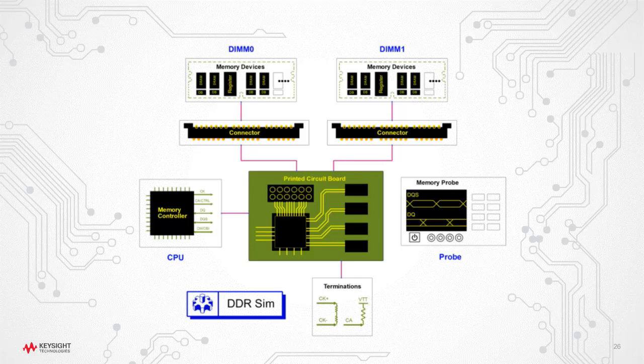Oh yeah, sorry, we just covered that one. So the short answer is yes, it can, and the longer answer is that for DDR5, you need to be able to run transient to capture the characteristics of the jitter and amplitude noise, and then put that into the DDR bus simulation.